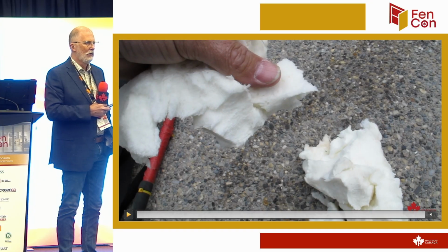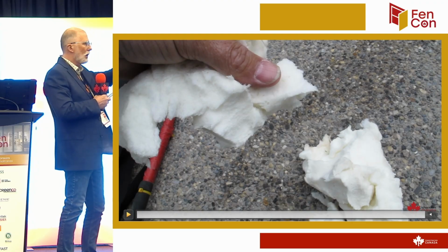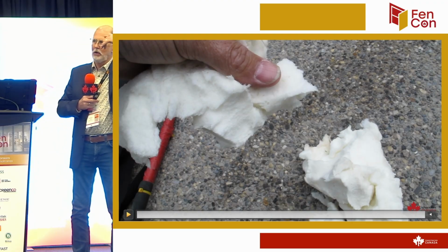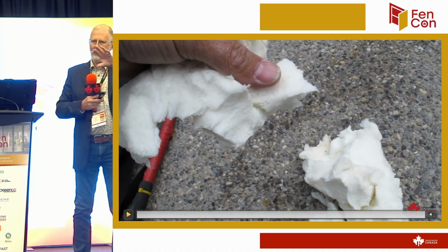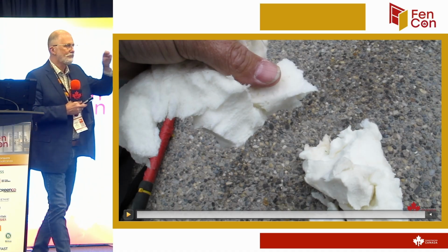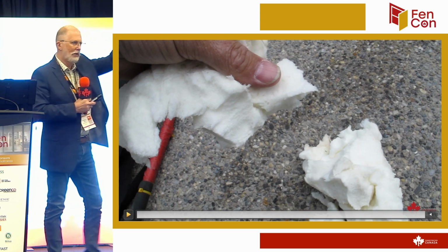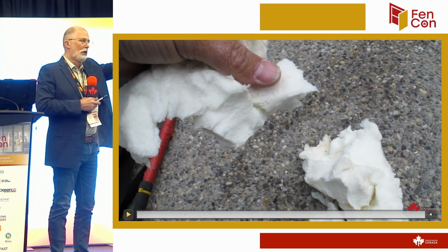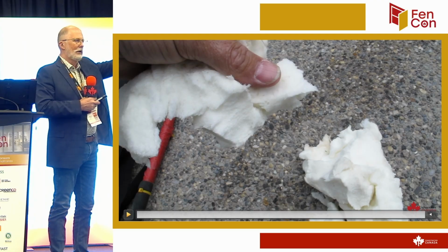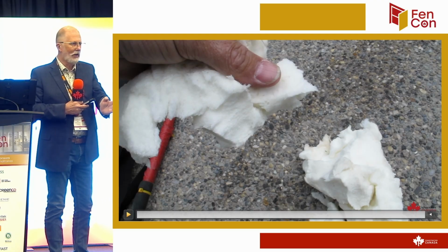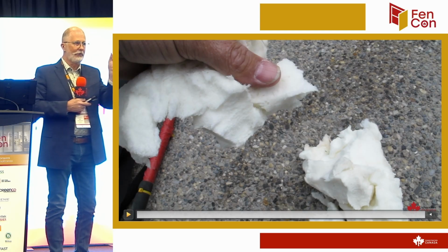Right. So if you think of the cross-section of the window, the question is, how do you know that the water that's coming in isn't just going to bypass all that air barrier you put in there? If you think of the cross-section of the wall, where could the water possibly come from? It could come in the middle of the wall, but how does it get there? It's going to come down the inside of the sheathing, it's going to come down on the outside. If the window fails, where does the water come?